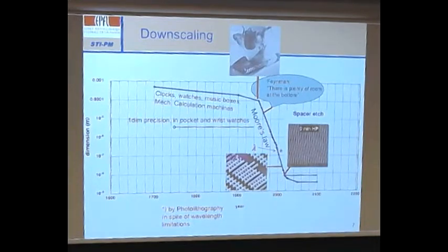You see here some pictures. These are 19 nanometer half pitch structures. So these lines are 19 nanometer wide, 9 nanometer wide. So this is what we can do. This is from ASML, this leading lithography company from Holland. That's one of the highlights in semiconductor industry from Europe, lithography, in fact. You have to know optics. In fact, the optics uses the theory of that time, Ernst Abbe or something like this.